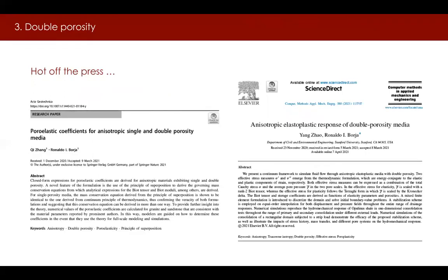In this third part of my presentation, I will highlight the multi-porosity of shale and the vast range of its pore sizes. Multiple porosity models compartmentalize the various storage and flow mechanisms into separate groups in double, triple, and even quadruple porosity models. Our work is limited to a double porosity description encompassing the deformation and flow mechanisms. Being a nanoporous material, shale permits fluid to flow through its nanopores as well as through distributed microcracks, resulting in preferential flow patterns and associated deformation mechanisms.